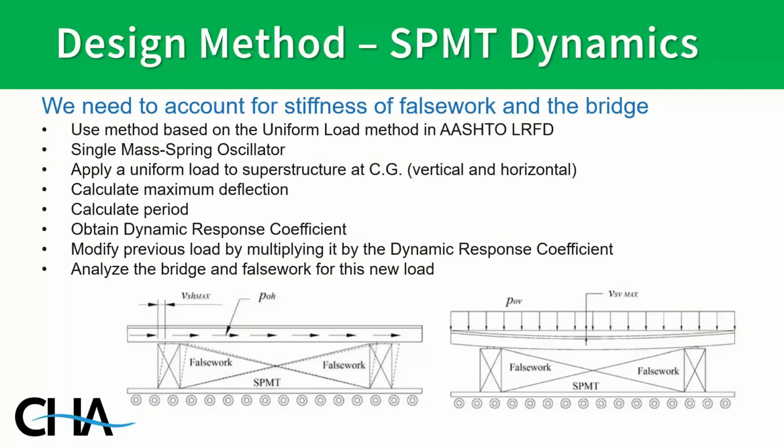As far as how to calculate these forces, we want to keep it simple, not make it too complicated. In theory, you could do a multi-mode spectral analysis of the system. Reality is, this is temporary work, so let's keep it easy. So we decided to use the uniform load method that's been in the AASHTO LRFD for years. That's based on the bridge acting as a single mass spring oscillator.